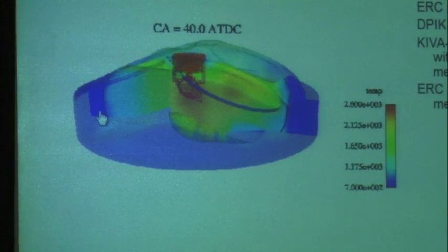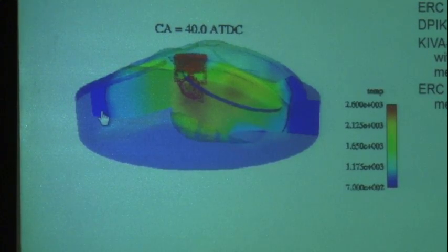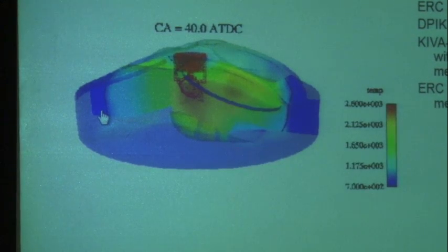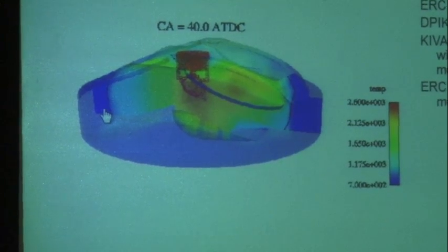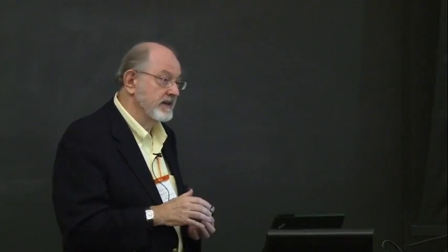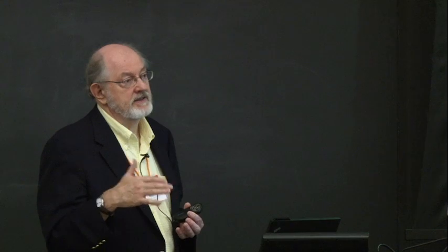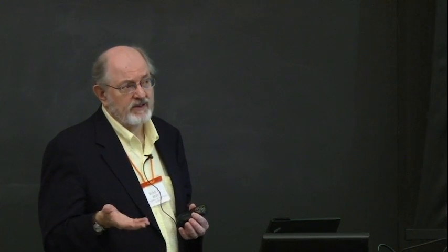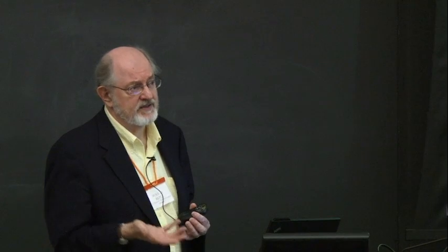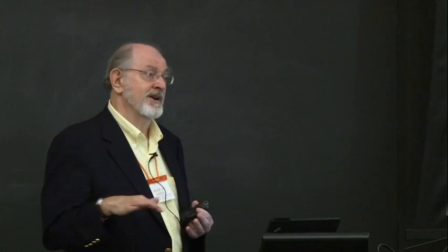Here's another question. No. We should, I guess. I did mention yesterday that we are looking at fuel films that are formed in an engine like this, where you'd have a fuel film on the piston. We consider that film and its vaporization and pyrolysis to produce soot, but we don't consider chemistry between the surface and the film, which would be important if you were trying to predict deposits, for example.